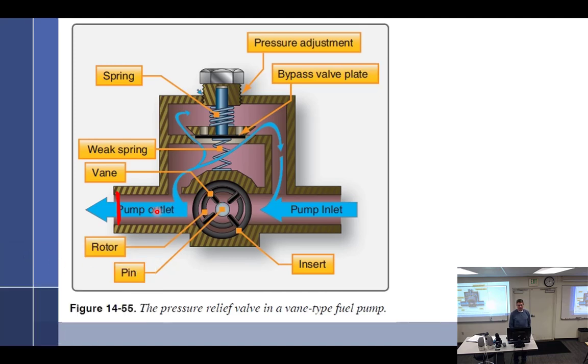It's going to come up through here, hit there, come up, back through here, and go back to the side of the pump. So you can sit there and do that all day. Comes up, pushes on this plate. This plate goes up, pushes against this spring. That comes around. Now, if I want more pressure, well, we'll do this now.